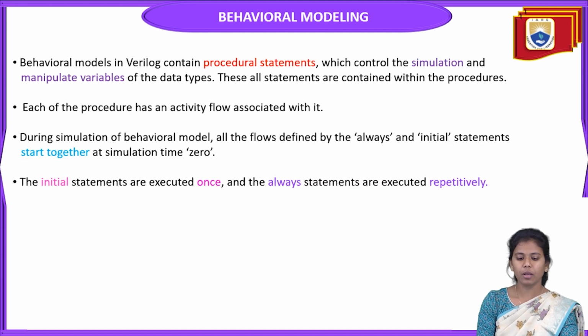And coming to the next point, behavioral modeling in Verilog contains procedural statements. Why does it contain procedural statements? In order to control the simulation and also to manipulate the data, the variables of the data type. Also, each of these procedures has an activity flow associated with it.